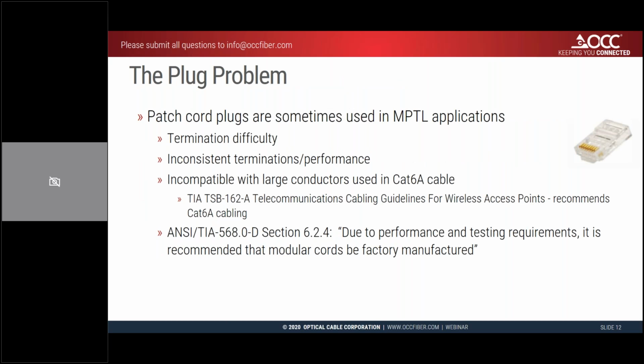All right, so there are some problems with mod plug terminated links, and one problem would be the plug. Sometimes people are trying to use patch cord plugs for MPTLs, and the reason this isn't a good idea is there's a few reasons, but one, they're difficult to terminate if you're not very skilled with it. You might actually make the connection, but getting the performance out of it, good luck. So there's inconsistent terminations and performance associated with that.